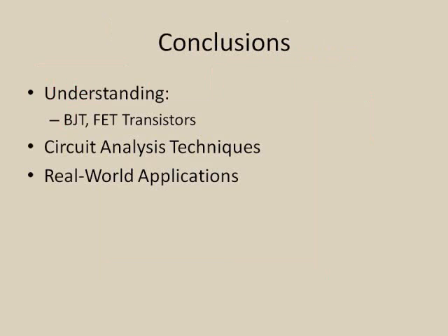In conclusion, although we were unable to finalize our amplifier circuit, we did manage to build a functioning amplifier before some part of the system failed. If we had been able to restart the circuit after the demonstration video had been recorded, it would have been a simple matter to deal with the distortion in the circuit by increasing the capacitance in the preamplification stage.